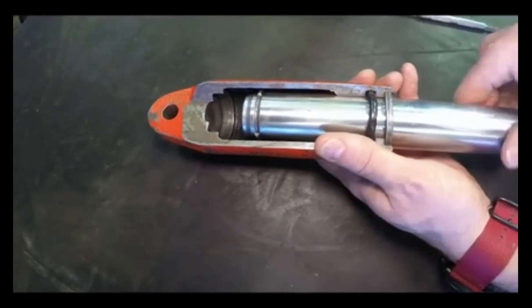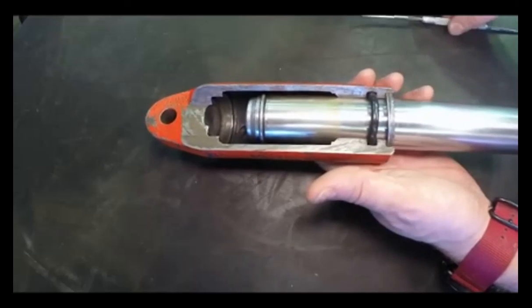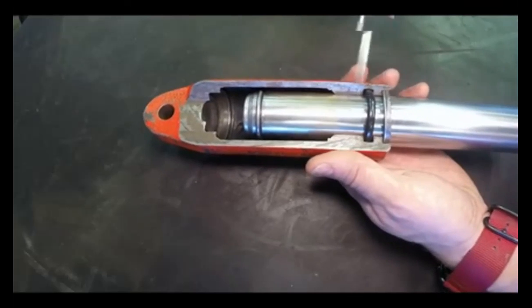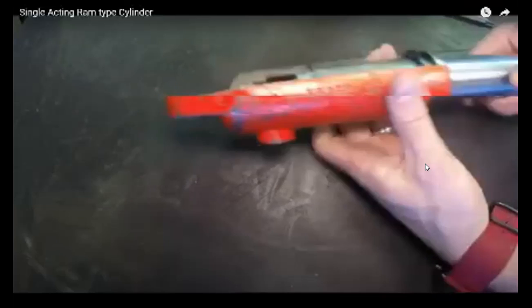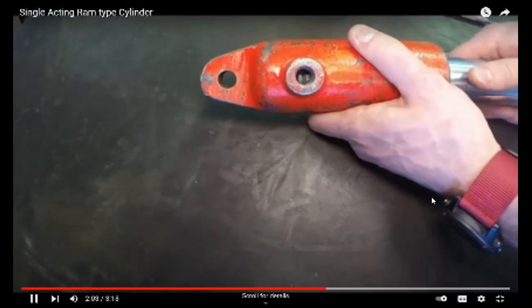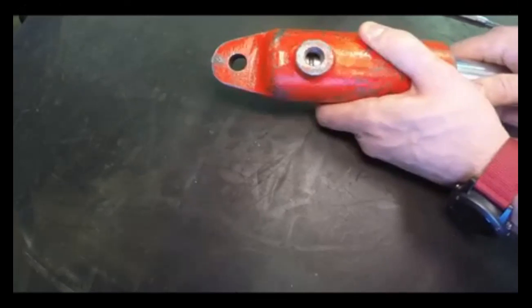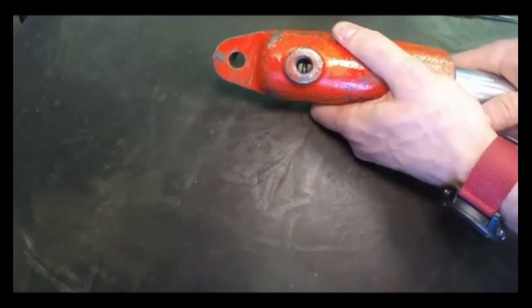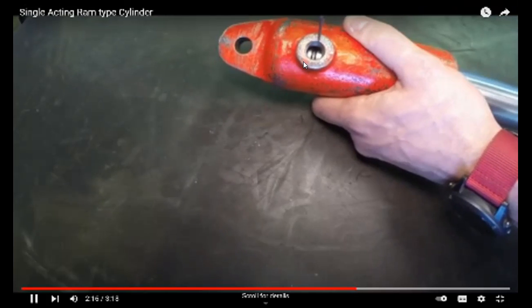Some of you will see these types of ram type seals or ram cylinders used on portable presses, and they still are able to create quite a large amount of force because they use a high pressure seal in there. To service these, you actually get into the back side right there, and you can see that the snap ring is accessible right there. You can see the end of the snap ring is just accessible. I'll just turn it so you can see the end of the snap ring. And what you can actually do is get on it with a seal pick.